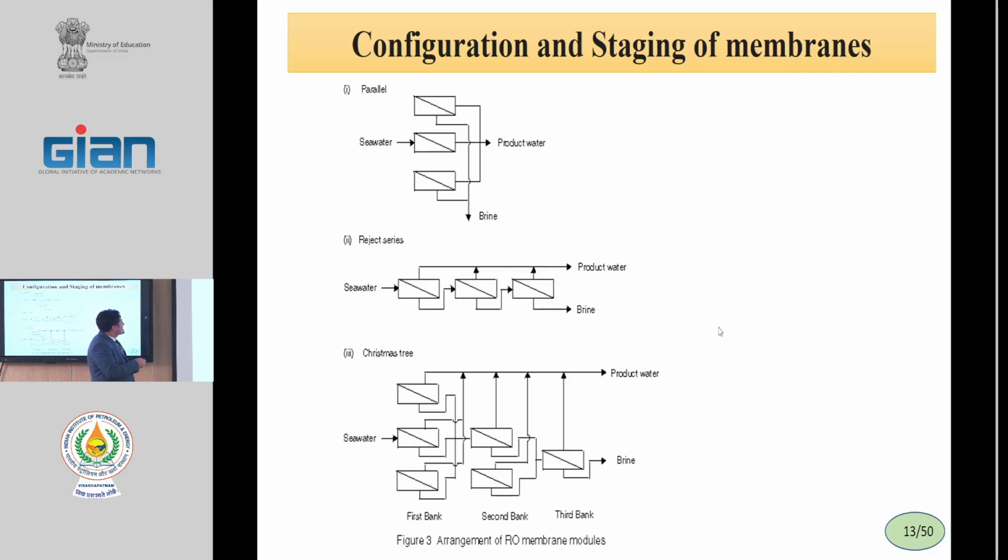But in the second configuration, for increasing the recovery, I said that we have a usual recovery of 60, 70 percent in reverse osmosis. For increasing recovery, we can use the concentrate of the first step as a feed step in the second.